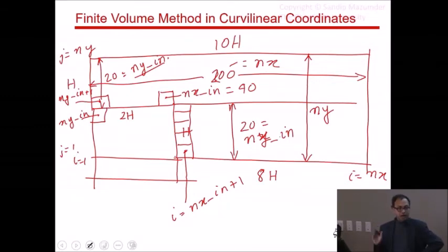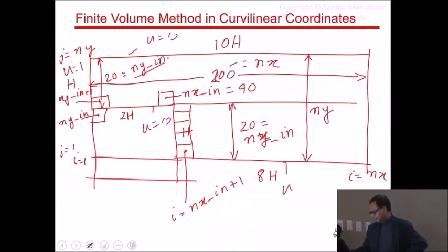First iteration, after you have solved your momentum conservation equation, you should see values bounded between, so suppose u is equal to 1 here, u is equal to 0 on all these walls, and you solve just the momentum equation to machine accuracy, you should see all your u velocities bounded between 0 and 1. There should not be any bulging or any of that. So check for that.